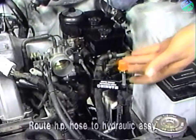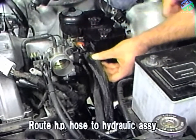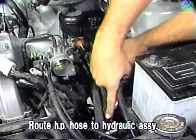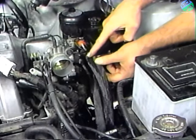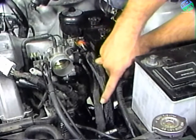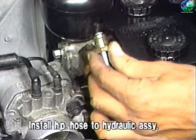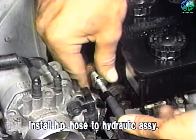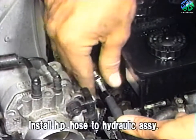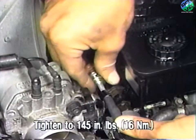After installing the connector block to the pump face, route the high-pressure hose along the left of the low-pressure hose and over the low-pressure hose to the hydraulic assembly, as shown here. Again, for visual clarity, some wiring connections have been moved aside. Next, remove the cap from the fitting on the supplied high-pressure hose and install the end of the hose to the hydraulic assembly. Tighten the fitting to 145 inch-pounds or 16 Newton-meters torque.